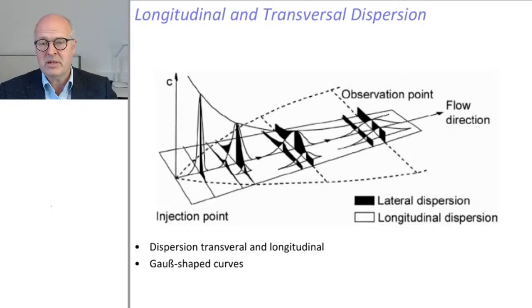When you do your first measurement, there is less dispersion yet, and when you do measurements at a later time, there's more dispersion. Because of that, your curve is asymmetric. So remember, concentration versus time, or time versus concentration, is asymmetric. Concentration versus space is symmetric and bell-shaped.